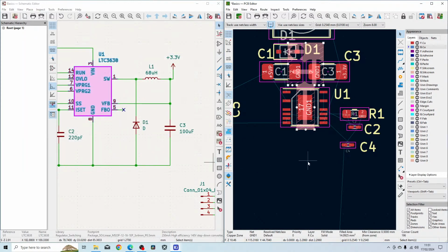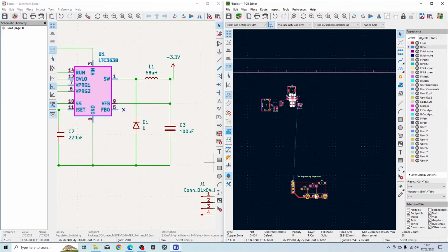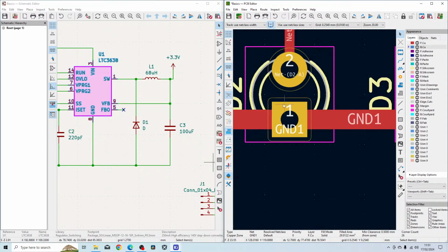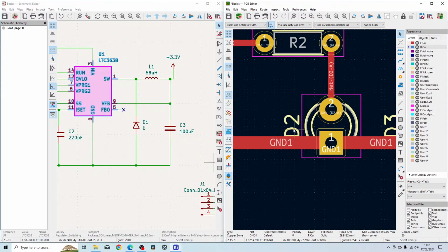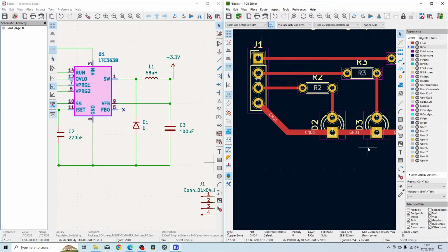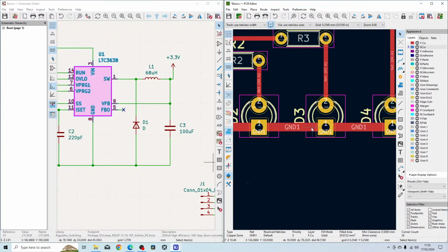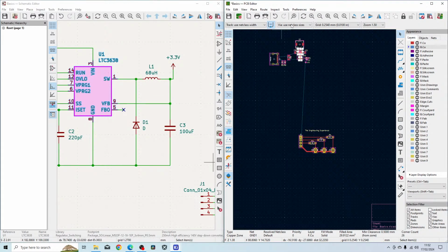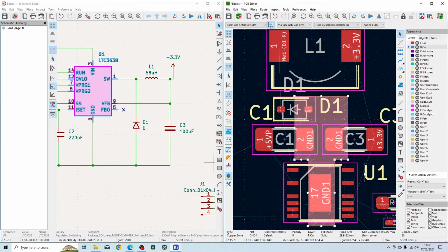So let's look at, for example, the part we had here. If I had a full copper layer on this node here, it would be relatively more difficult to solder this part up, because you would need to hold your soldering iron on it for a lot longer, because all the heat would be just dissipating in the copper. So obviously I'll remove the thermal relief, so you can see now it's just a solid plane.